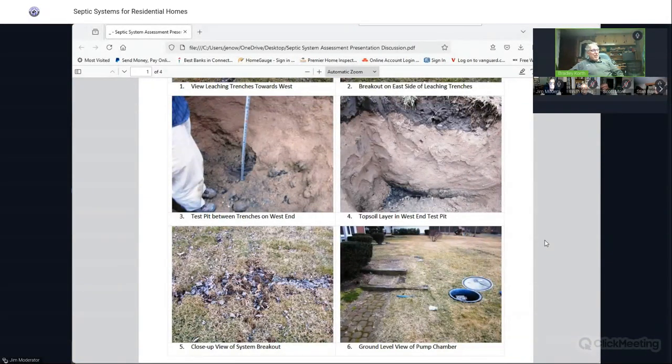that was a partially exposed finished basement. And what they were doing in this house, as happens in a lot of houses, is that if they have a bedroom or a bathroom in the basement, they're supposed to have a separate pump chamber just for that effluent. What it should have, and I'll show you in a subsequent diagram, is the flow coming out into a large pump chamber. If they're going to put all the flow downstairs and then pump it out, have a large enough pump chamber, or have a separate line coming out of the house. So we can go to the next pictures.